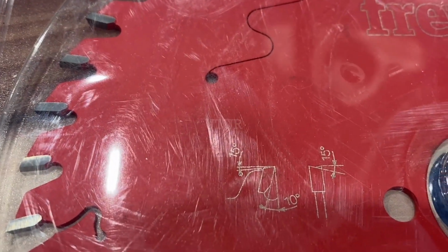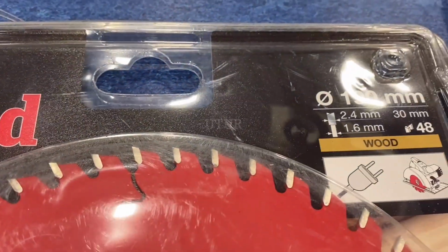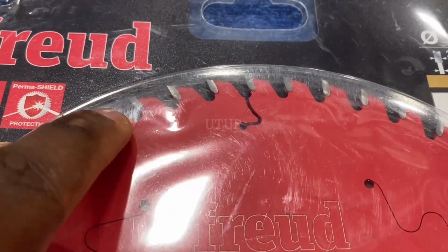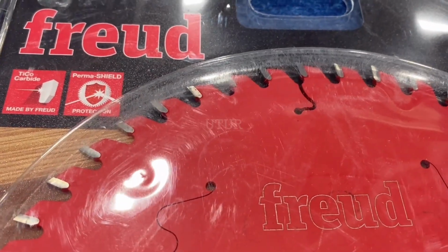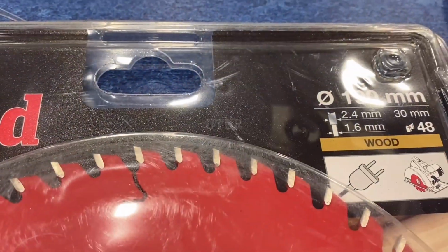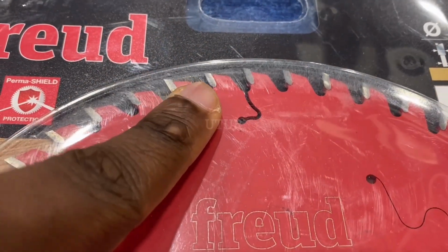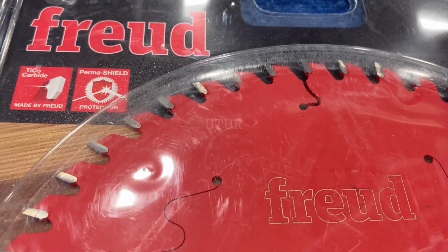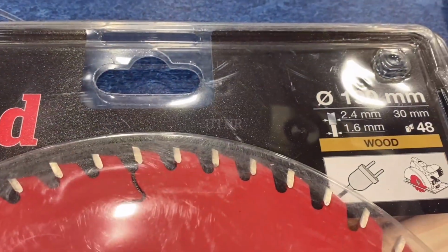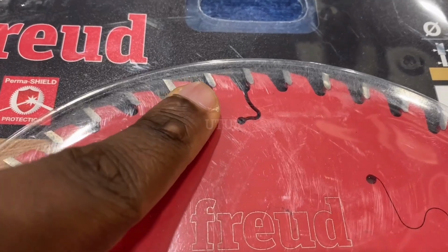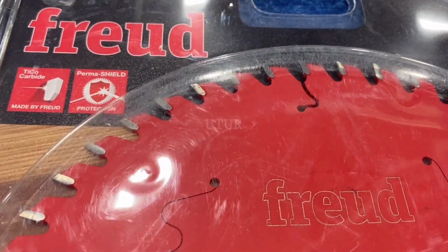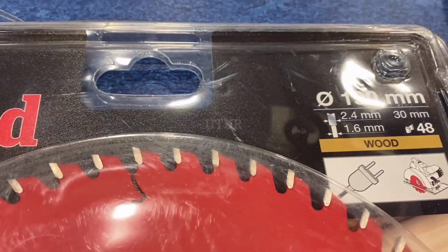As opposed to economy blades, which have got the open hole technology and stamped blades with small teeth, this quality blade has got bigger teeth or tooth sizes. It's got a hook or rake angle of 10 degrees, so it's not a very aggressive feed, as the smaller the hook angle, the more pressure is required to feed the workpiece. The previous blade has got a slightly more aggressive feed, as the hook angle was 15 degrees.